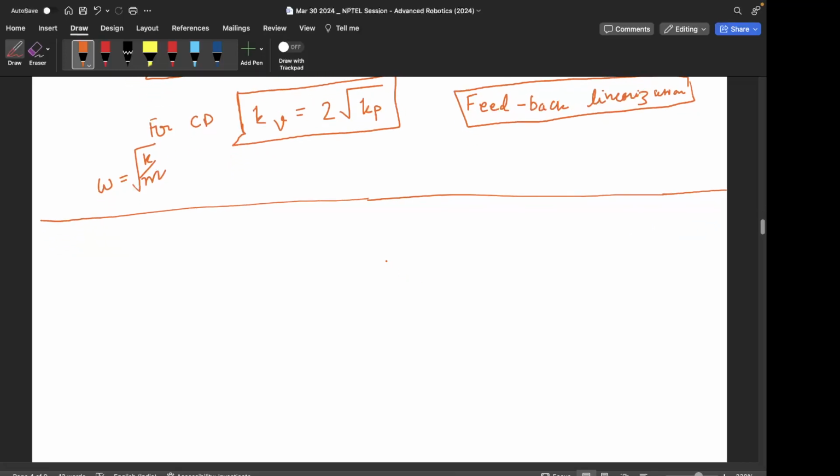So till now what we have seen is single input single output systems, and we have essentially designed position regulator systems, so that if we want that block to be at a certain position, x is equal to 0, let's say, and it is able to counter disturbances and displacements away from its position, it comes back to its desired position, right? And we can very easily extend this approach itself for trajectory following.